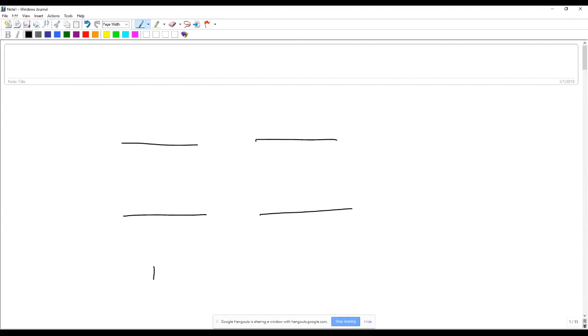So I have a P plus. We usually use plus to denote heavily doped or degenerate. I have a P plus and an N plus. Here my Fermi level is in the valence band. If you remember from earlier, we were always drawing the Fermi level between EC and EV. And now I'm drawing the Fermi level below EV, in the valence band.